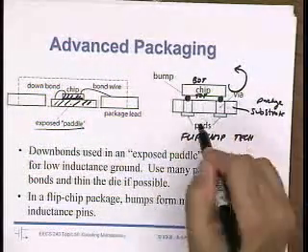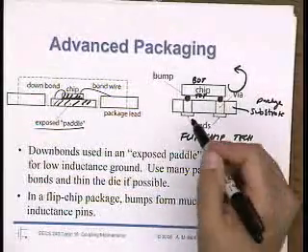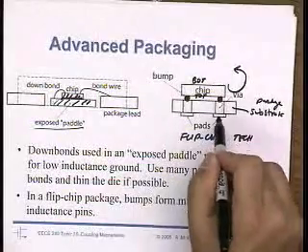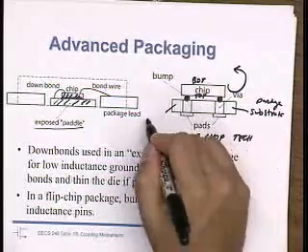And the second chip can be made of many different materials. It could be FR4, what you're used to, the same material as the board itself. It could be ceramic. It could be low temperature co-fired ceramic, what's called LTCC.